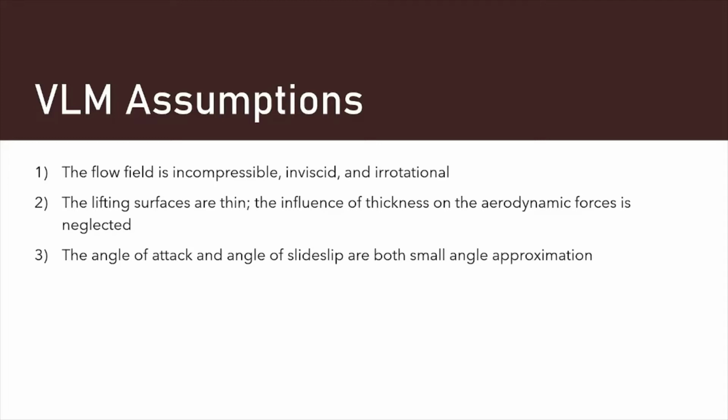So the lifting surfaces, as you can see, are thin. The influence of thickness on the aerodynamic forces is neglected. See, what makes VLM different from panel method, for instance, is that the lifting surfaces have a thickness for panel method. And not in this case, but the camber is still factored in. And also, the angle of attack and angle of side slip, oh, there's a typo, side slip, are both small angle approximation.